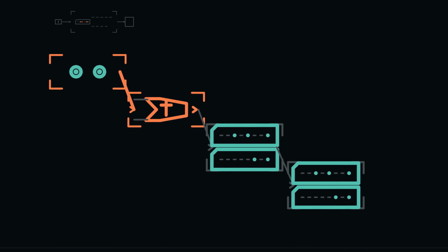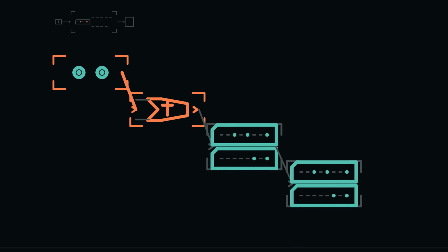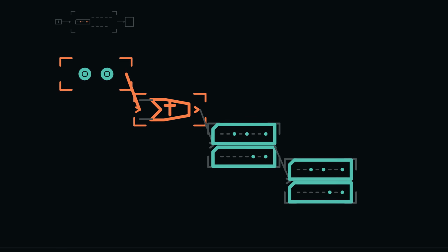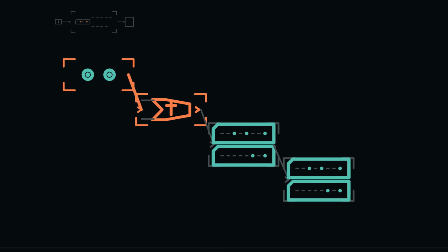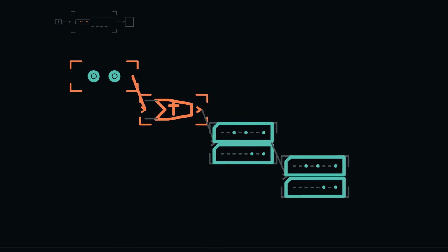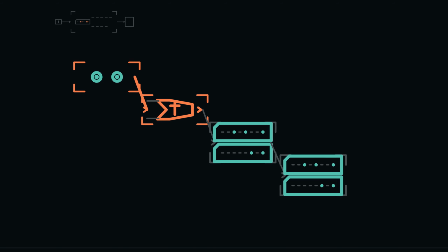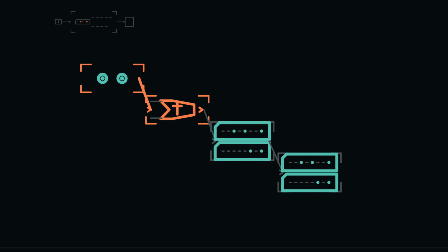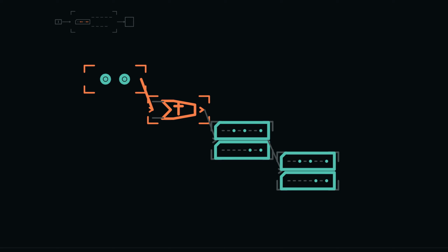The ordinary fetch copies 29 into the first instruction register and 05 into the second. Decode separates opcode, register field, and immediate mode bit. Execute routes R0 and the immediate 5 into the arithmetic unit, then captures the result back into R0. Every layer has now met the same state change, but only the encoded instruction bytes were fetched by the machine.